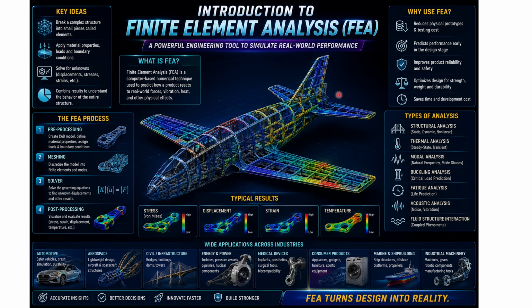FEA is a kind of tool where we can apply our loads, boundary conditions, temperature, pressure, vibration, forces, heat, and we see virtually how the component or product is going to behave for these different conditions of loads, heat, pressure, etc.